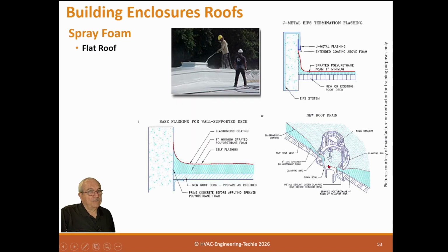Spray foam. Spray foam is good for flat roofs or specific sealing problems. Protective top coat: it has to have a foam. Sun will degrade raw foam, so it has to have some kind of white cap or another kind of cap. Gypsum. Sometimes I've seen them put liquid gypsum on it that dries hard. That's good. Also, foam is very fragile. You take a screwdriver, you can go right through foam. Even if it's got a white cap on it, you go through that. If it has a gypsum cap, you can't, but this can. So foam is a very good seal. Again, it seals tight. It seals everything, but you have to be careful with it also.